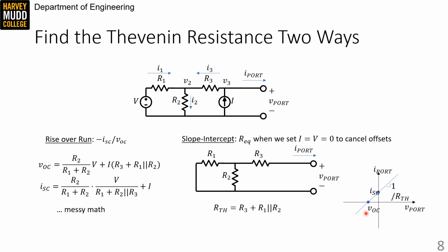Also, as one quick definition, I told you a partial definition for passivity, which is zero voltage for zero current. Technically, a circuit element is passive if it exists only in quadrants 1 and 3 on the IV plane. That means that it produces no power when zero voltage is applied, and power is dissipated in it in the first and third quadrants. If an IV curve passes through quadrants 2 or 4, then it's technically generating power, which means it's no longer passive.